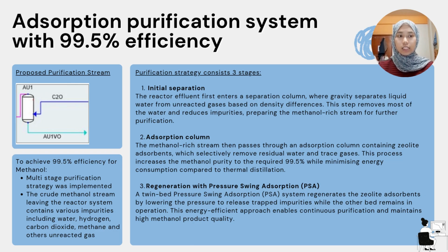The last stage is regeneration with pressure swing adsorption, or PSA. A twin-bed pressure swing adsorption system regenerates the zeolite adsorbents by lowering the pressure to release trapped impurities while the other bed remains in operation. This energy-efficient approach enables continuous purification and maintains high methanol product quality.